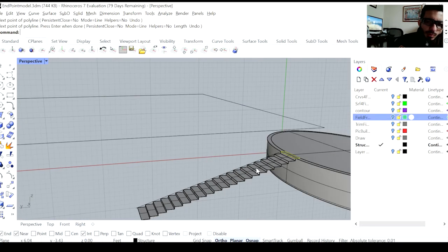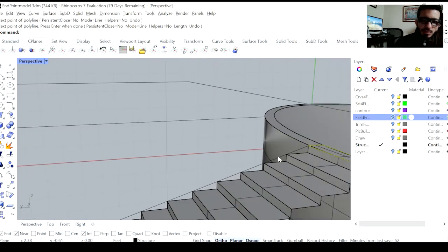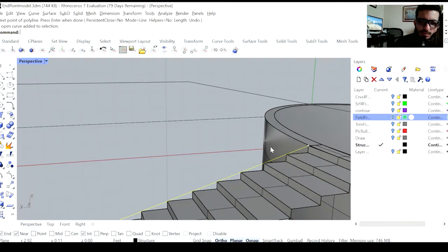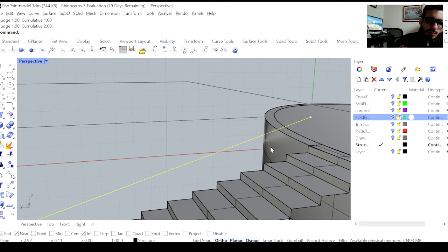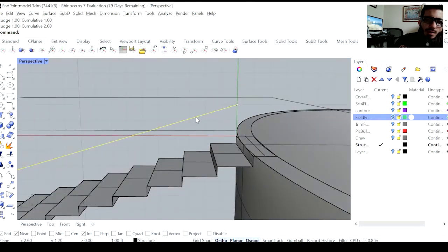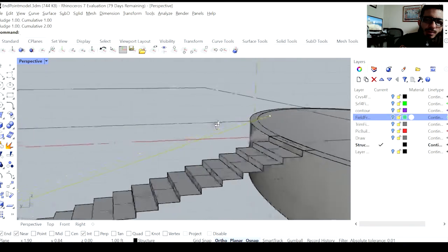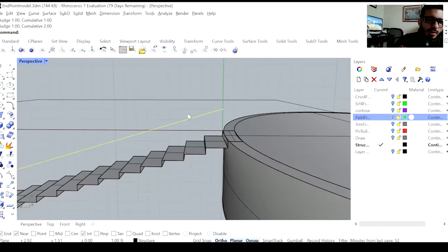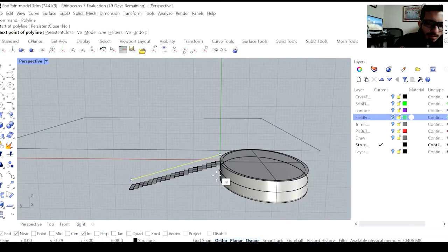Since we want to create a surface instead of just a rail, we're going to move that 2 feet up, which seems to be okay. And then we are going to create the polycurve from there. So straight down. In fact, let's go ahead and start from here.